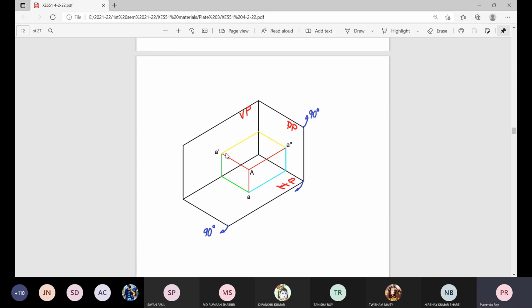Now this 3D like model presentation will not help us. For a particular point, you need three cardboards. You have to glue them together mutually perpendicular to each other. That is a difficult thing and not practical also. So what we need to do is present these three different views projected on these three different cardboard like things in a 2D shape. That is, you open this 90-degree first angle space or first quadrant by rotating this horizontal